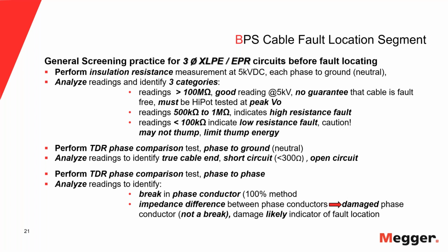And what that means is if I have a 35 kV circuit, 20 kV phase to ground, that's RMS. So if I only use 20 kV DC to high pot, it's not going to be good enough because my peak voltage is 28 kV. So I have to at least test up to 28 kV DC to see whether that cable has an issue. And even then, if that turns out to be good, it's not the ultimate answer whether the cable is good or not, because if I had an open conductor, I could even have a much bigger gap, which would require even a higher voltage than the phase to ground. The phase to ground voltage, peak voltage, is only good for basic pinhole faults.